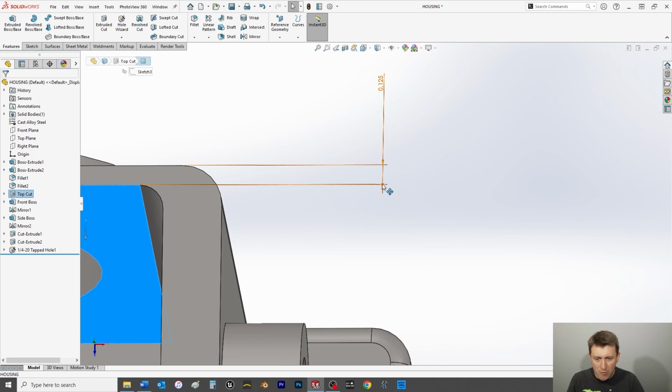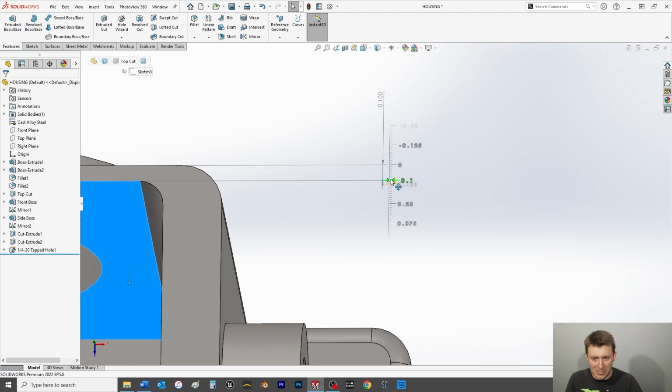Now if I hover over it and I click and, still holding, drag over to the right, so now I'm on that little measuring ruler that we see here, that way I can drag in precise increments that we set, which you would have noticed from the Instant 3D we did in a prior video. So as I move this, it's ticking in precise increments of a dimension change.